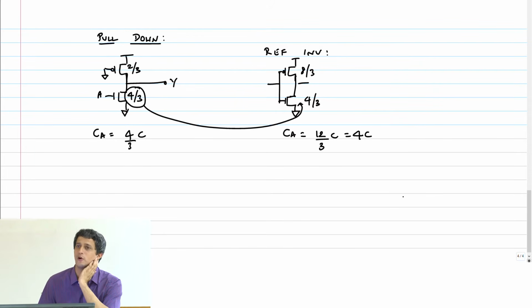So, is the logical effort 1/3? Again, go back to how we constructed the unit inverter. The question is not whether the resistance is equal. How much current is available to the load capacitor for discharge is what matters.